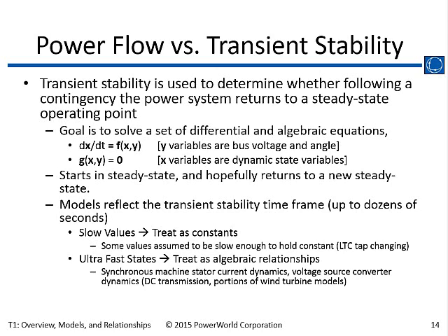So usually in a transient stability run, we don't have dynamics in for the taps on the generators, the LTCs, that can be such a pain to deal with in the power flow. They tend to be held constant during a transient stability run. You can include dynamics, and we've coded up dynamic models, but usually they're not included.